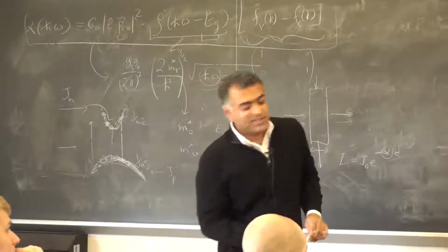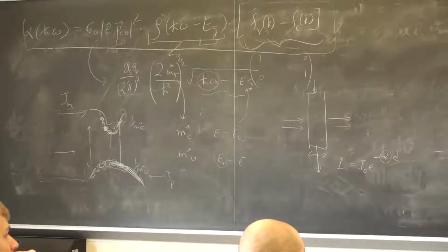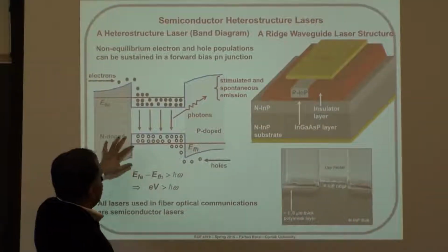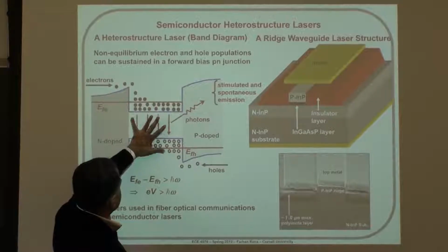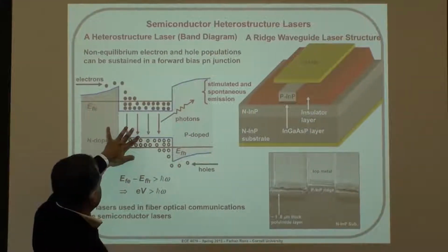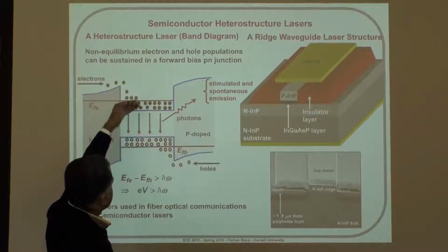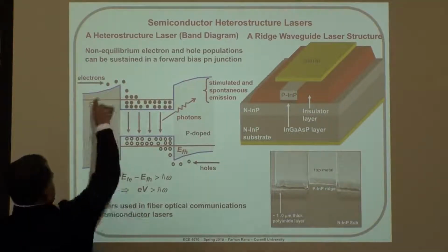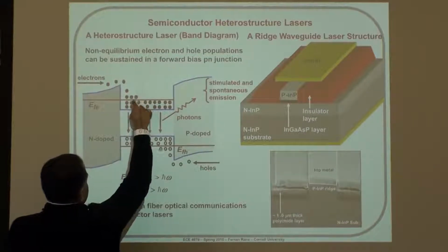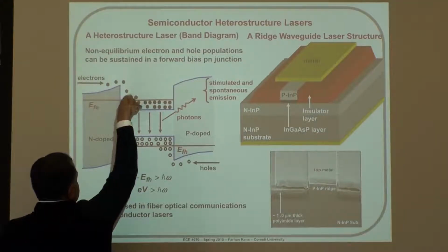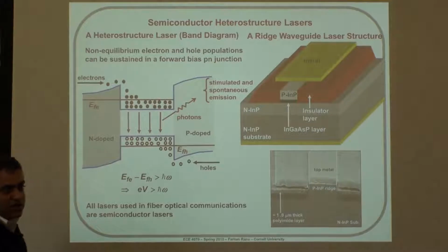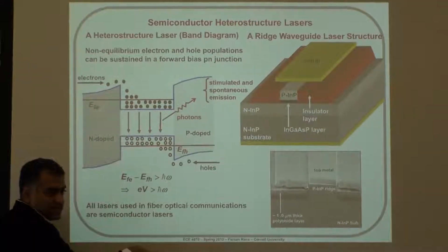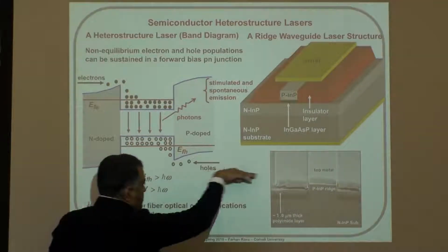Just a second, and then this is a picture. In pictures are energy band diagrams, how this process is created. And remember, if I have photons coming out here, there'll be transition from conduction to valence band here, but after you inject, physically, what you're really doing is the electron comes in, drops here and then drops here. This process is going to just emit some phonons, and it's going to heat. This process from here to here is going to create light. And then that electron is going out that way.